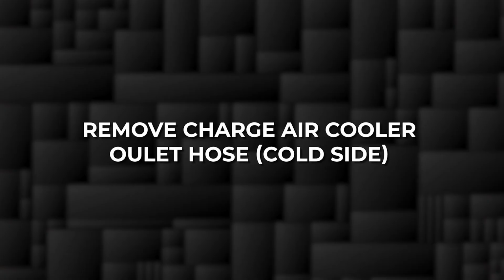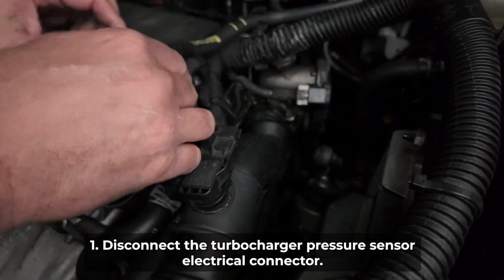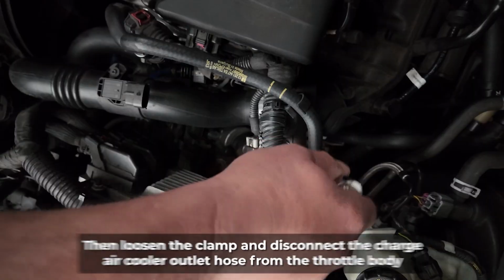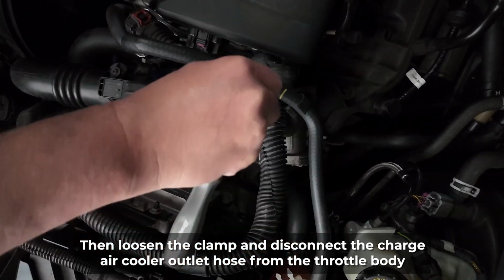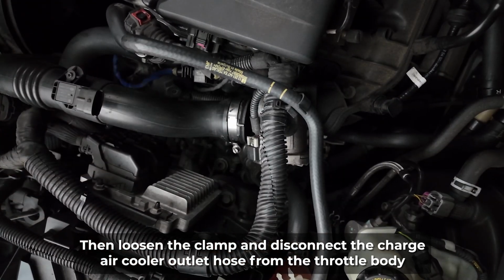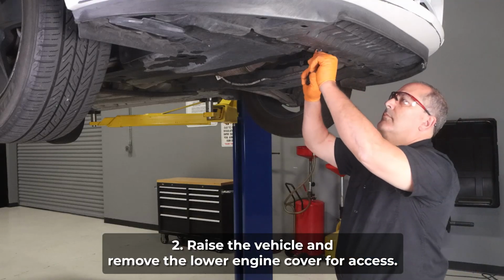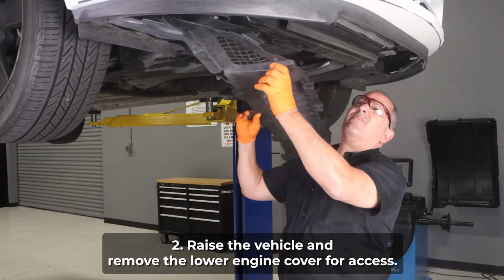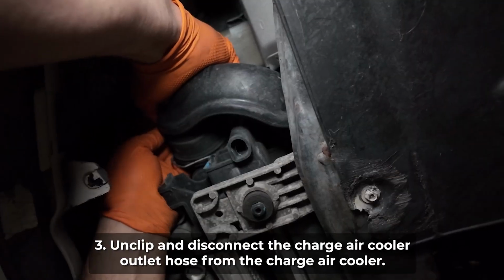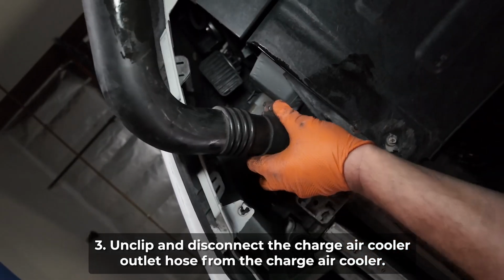First, remove the charge air cooler outlet hose. Disconnect the turbocharger pressure sensor electrical connector. Then loosen the clamp and disconnect the charge air cooler outlet hose from the throttle body. Raise the vehicle and remove the lower engine cover for access. Unclip and disconnect the charge air cooler outlet hose from the charge air cooler.